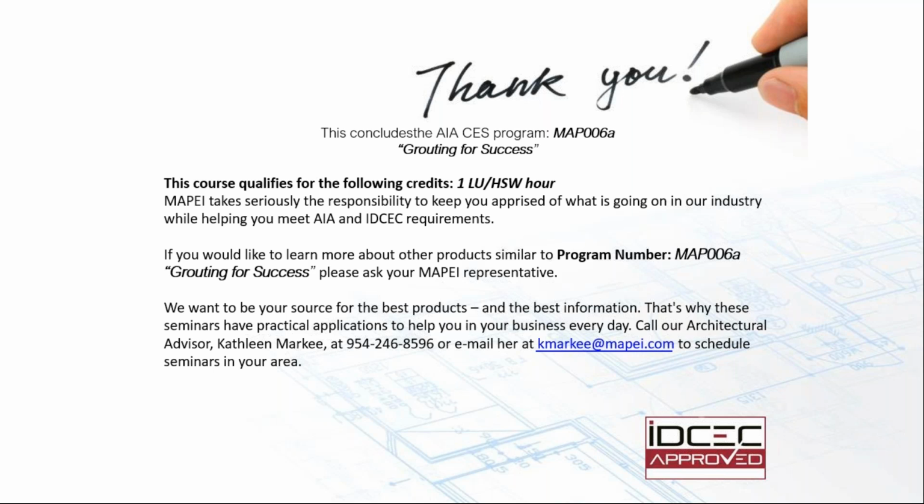Grout is the same way. Although you've picked out a beautiful light color, over a period of time, as you're walking on it, dirt is being impacted into the grout and it's getting darker. So to help prevent grout from changing colors and getting darker, sealing should be done on any type of cement grout, whether it's a Portland cement or a calcium aluminate cement grout. It is still a cement grout, and it should be sealed.